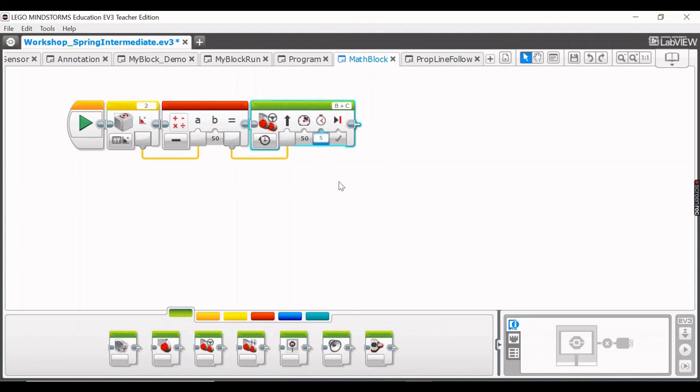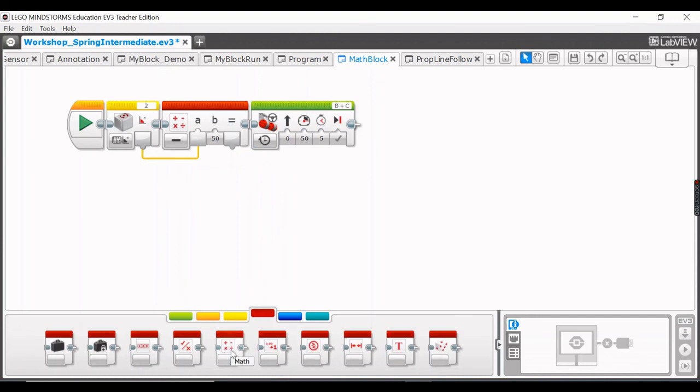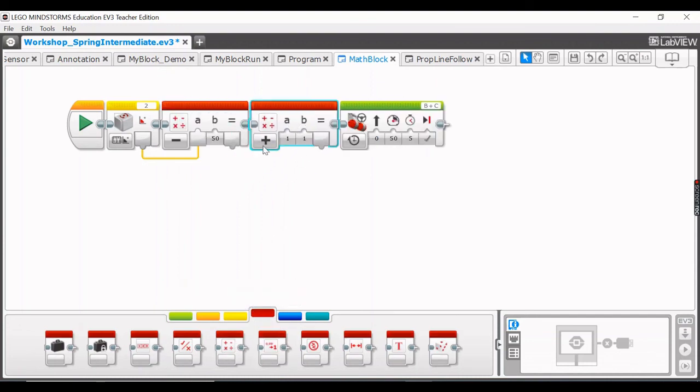And if it's not at a gyro angle of 50, then it'll do some steering to get back on course, assuming we multiply it by a negative 1, because the gyro sensor needs to be inverted. Otherwise, it'll keep on turning in the direction that you have it coded in. Like if it started at 20, then it'll keep on going to 50, 30, 500, on and on and on.